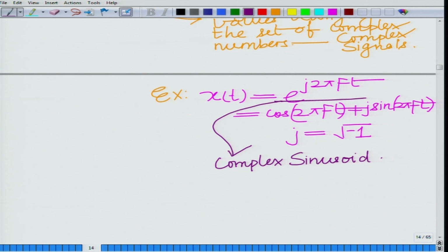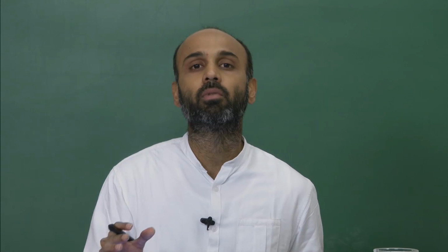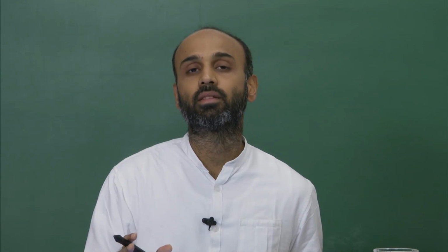Such signals are, needless to say, complex signals which are complex valued. They can take values belonging to the set of complex numbers. So, we have real signals or complex signals, and complex signals, although they do not occur in practice in the sense that they do not exist in nature, are very useful in the representation of signals. In fact, once again, if you go back to the analysis of communication systems, all communication signals can be analyzed or represented as complex signals, assuming the in phase and quadrature components of a communication signal.